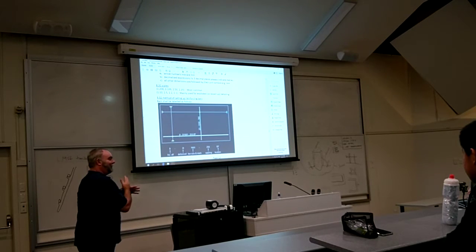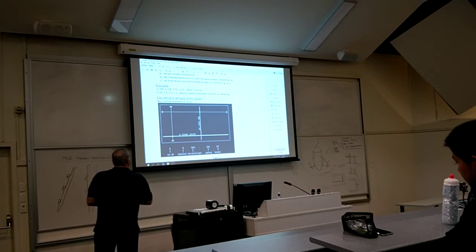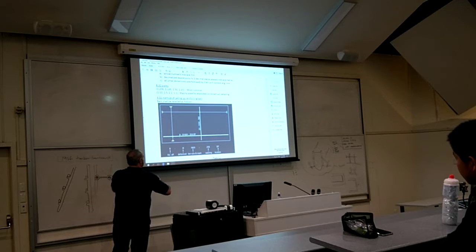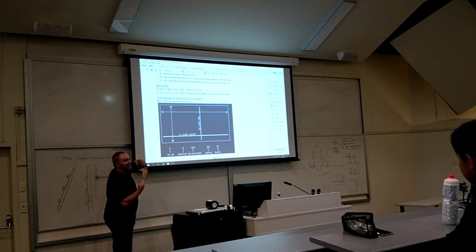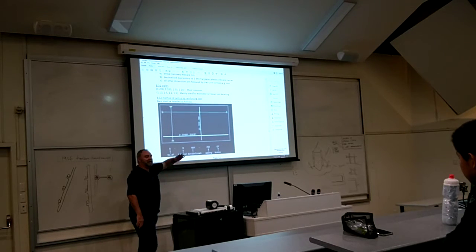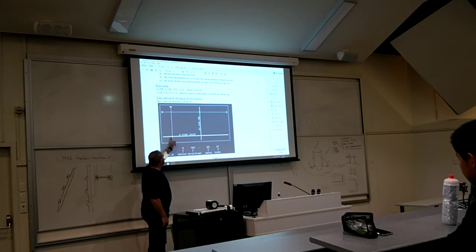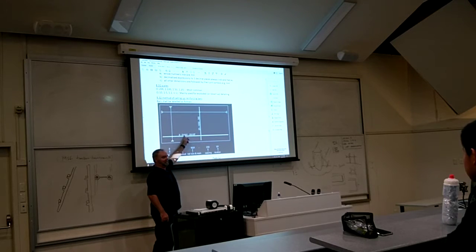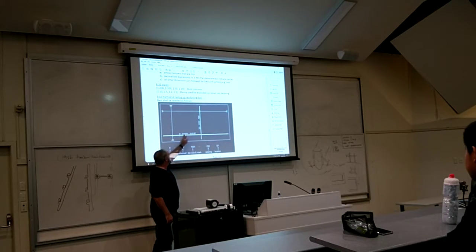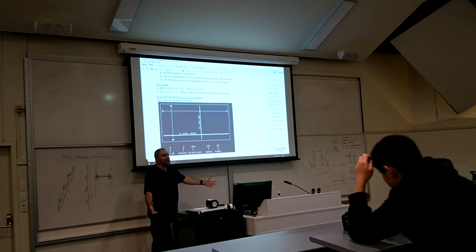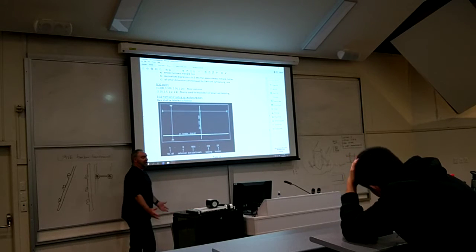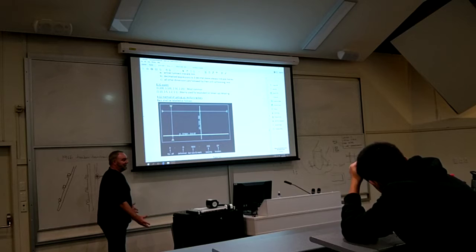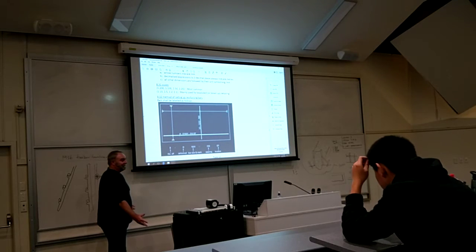Your assignment slab has got 1, 2, 3, 4, 5, 6, 7, 8. It's got 8 bars going in 2 different directions, and you must label them all without getting any of these lines through any of that text. You may put it through one of those, what I'm going to let you do. The reason is, if that line went through that number 1 and you printed it out as a PDF, you won't see the 1. And, like anything else, you'll pass that on to the steelfixer, and he'll think it's a D6 bar. Right?